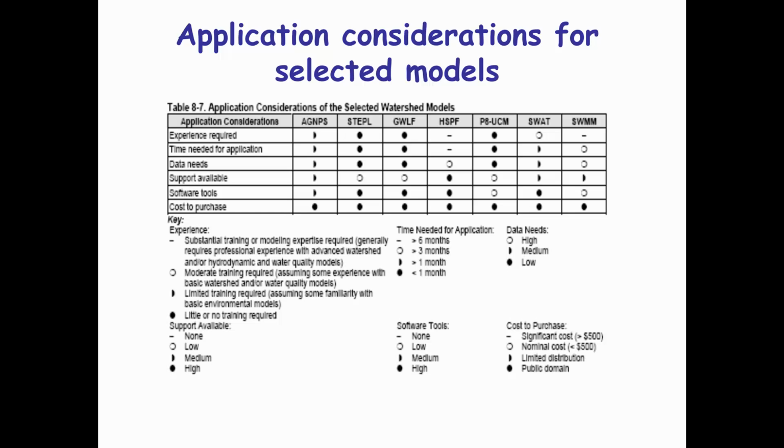The data needs are medium for the SWAT model. Software tools that are available are very high, so SWAT can be used, for instance, with ArcGIS. There's a thing called ArcSWAT that allows you to implement the model very readily, and the cost is the model is free. The only thing would be if you're using ArcGIS, there might be a cost using ArcGIS, but SWAT itself is free to use.